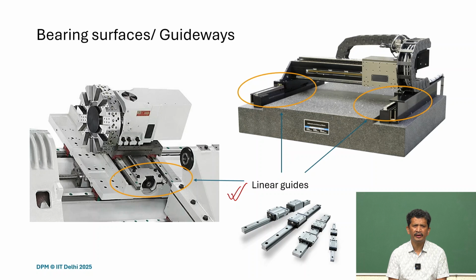That will be the limitation, the positioning uncertainty we get because of the friction and the limited stiffness of the component. So as long as there is some kind of physical contact, either sliding or rolling, we are bound to have certain hysteresis, and therefore we have a virtual play.